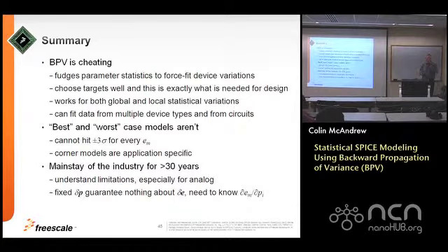You give it an input file and a set of models, and you have to tell it what the parameters are, and you have to give it a program that simulates the electrical performances, and this thing just runs, and then it spits out what the variances are. It'll tune the model in initially. It actually will subtract out mismatch variations if the mismatch models are in there. Remember I said variances add to fit the global variance. I've got to take the total variance that I get from my specification.